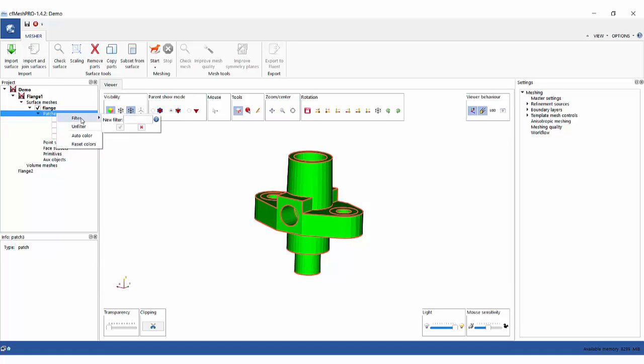This feature can be extremely useful, especially in those examples where there are tens or hundreds of patches defined in the surface mesh, and navigation through all the patches would be very difficult in those cases, unless there was a way to narrow down the number of shown patches. Of course, this feature is useful only in case the patch names are given in a smart and meaningful way. For instance, naming patches on the inlet boundaries as Inlet 1, Inlet 2, Inlet 3 or similar would do the work.